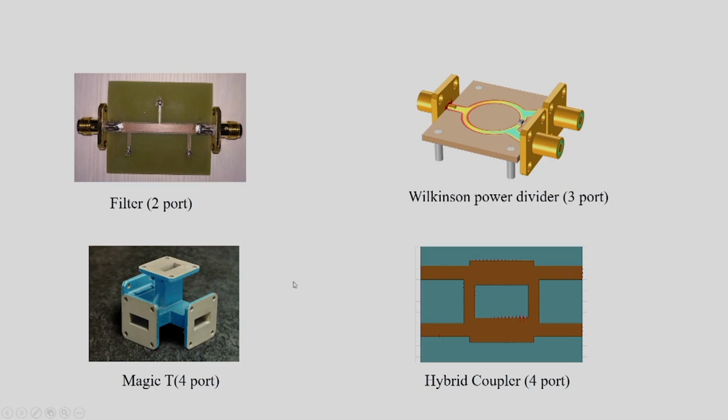So, you can see that physical microwave circuits or networks will have one or more ports, and we define the voltages and currents in these ports directly if they are TEM lines, or if they are non-TEM lines we can always have an equivalent voltage which is related to the transverse electric field, and an equivalent current which is related to the transverse magnetic field components.